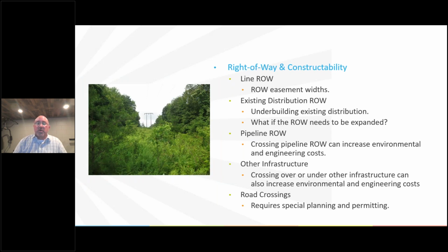The term constructability is used to discuss the feasibility of constructing a transmission line as it relates to engineering, right-of-way, and construction concerns. Constructability evaluates the use of existing infrastructure corridors, engineering challenges that might be encountered, and potential construction accessibility issues of a proposed route. Major factors that can affect constructability include, but are not limited to, steep slopes, condensed right-of-ways, sharp angles, proximity to major highways, accessibility, and cost.